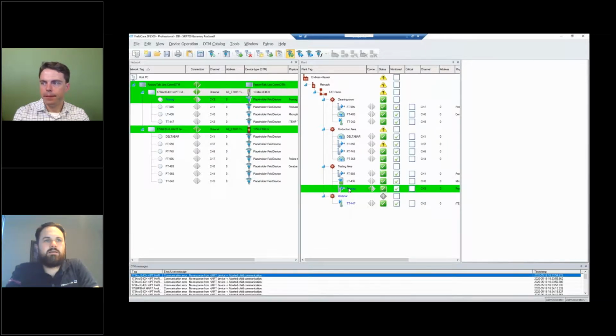Excellent. We've got another question from Anurag. He asks, does it support Siemens PLC as well? Siemens PLCs, let's say if it's a Profinet infrastructure, yes, we can connect to the Profinet, but we cannot route through Siemens PLCs as we can do with Rockwell. The reason for that is very simple: Siemens is locking it down.